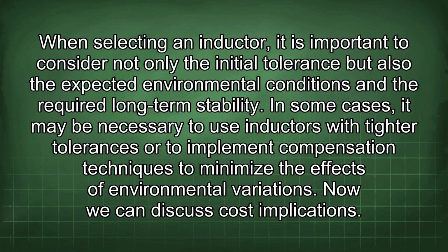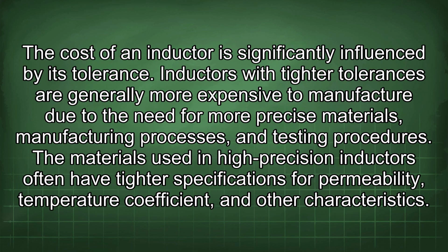Now we can discuss cost implications. The cost of an inductor is significantly influenced by its tolerance. Inductors with tighter tolerances are generally more expensive to manufacture due to the need for more precise materials, manufacturing processes, and testing procedures. The materials used in high-precision inductors often have tighter specifications for permeability, temperature coefficient, and other characteristics.